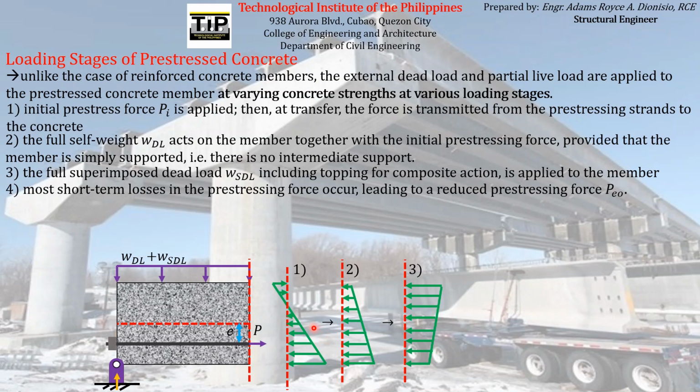So you can imagine that this magnitude of stress diagram here will now have a somewhat lesser magnitude, since the magnitude of the pre-stressing force will now have a lesser value due to the occurrence of the short-term losses. Although in this particular diagram we did not alter the diagram itself, just imagine that this diagram has already diminished in magnitude with respect to the stresses acting on the concrete element.